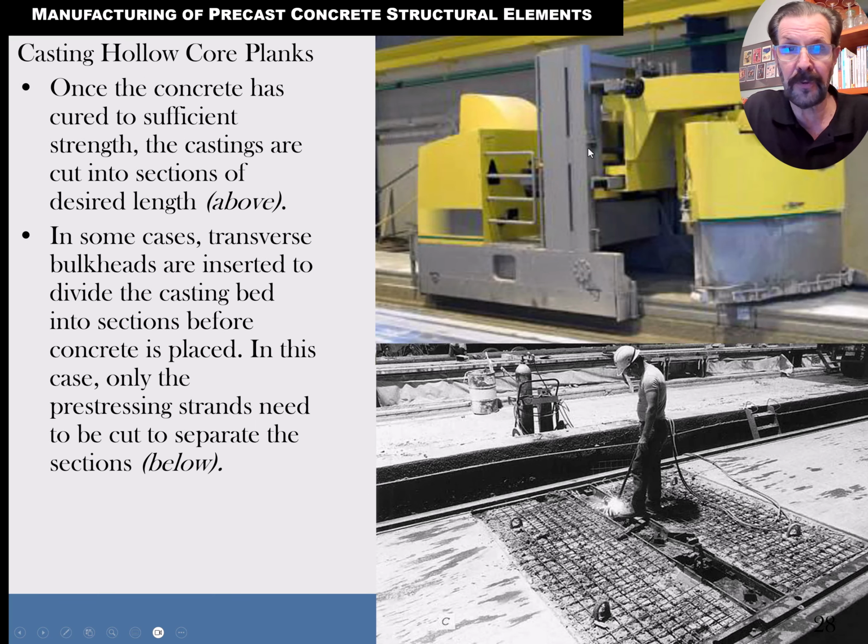There's that shaper that forms the hollow core slabs right here. Give you an idea of the shape. It's basically making those keyway shapes, and the concrete has just enough water for the chemical reaction, but not enough to slough away, so it holds its shape like a piece of clay that you're modeling. And then to keep it from drying out, they'll run the steam,